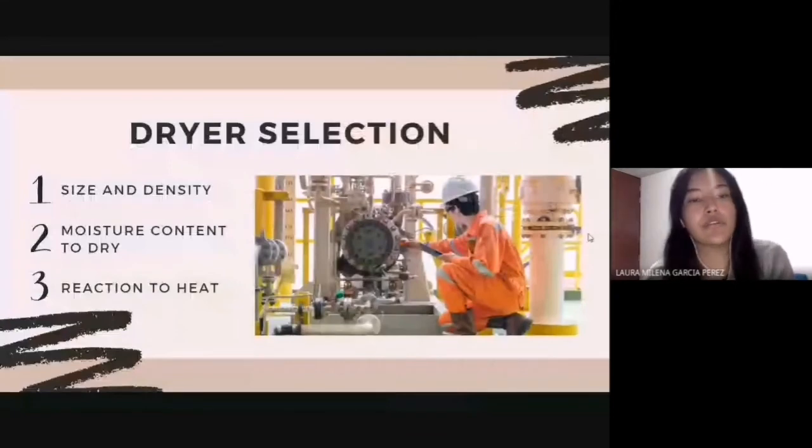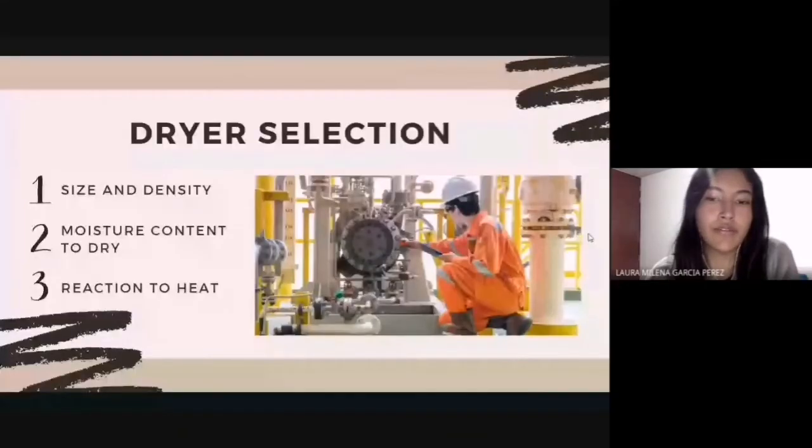Okay, so industrial dryers are an essential part of material processing, but they are generally a large capital expense and can last decades. This makes choosing the best dryer very important. The starting point should be to observe the size and density of the individual particles within the material being dried. A fine powder will require a different drying method than a material of the same size as mud. Second, although it seems very obvious, it is commonly overlooked: the initial and final humidity percentages must be known, as they are used to size the dryer.